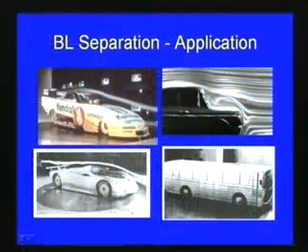There will of course be wind, and the wind effect will be there on the vehicle. So the surface of the vehicle is designed in such a way that the separation takes place at the rear end, and then the flow resistance will be much lesser. You can see how the shape of the cars has evolved: earlier, in the 1950s and 60s, their design was like this, and now you can see the latest design of the vehicles here.